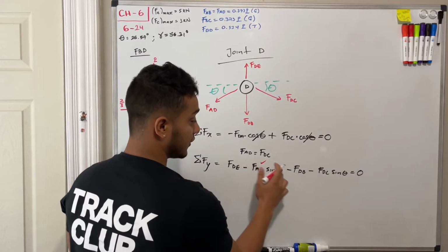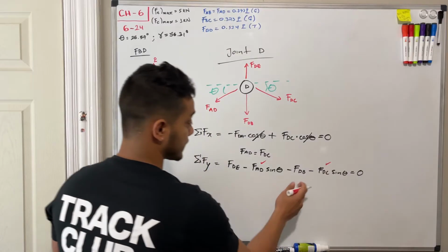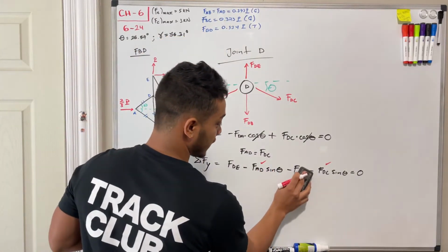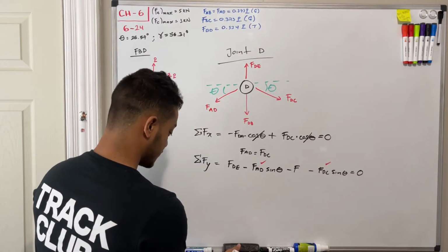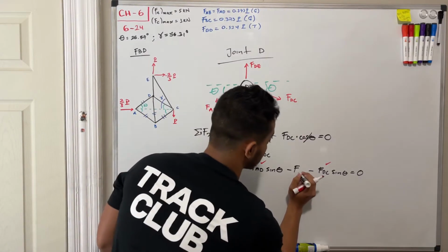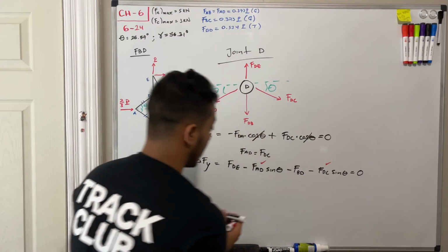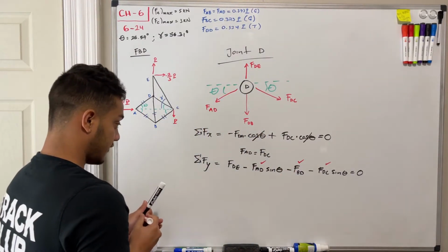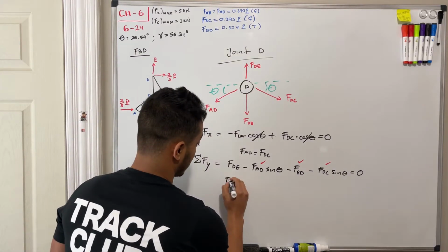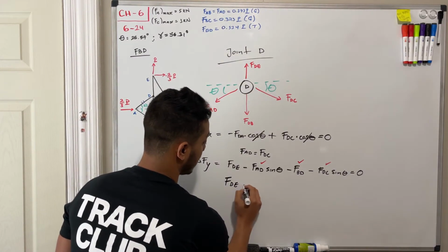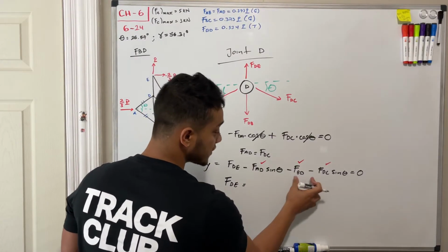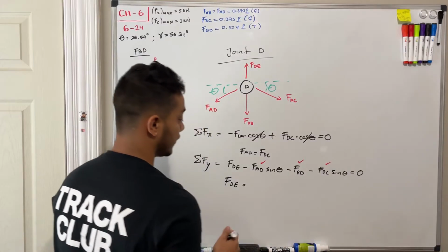Yes. Do we got the value of DC? Yes. What about BD? Yes, we got it. It's the same little nomenclature mistake I make over here. So this is BD. Therefore, we got the value of this guy, and we can solve for my force DE. It should be equal to the addition. If we pass this guy, it will become positive, positive, and positive to the other side.